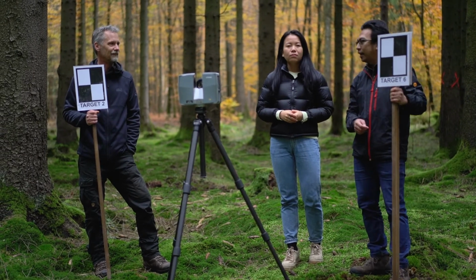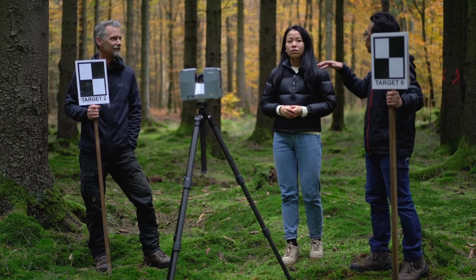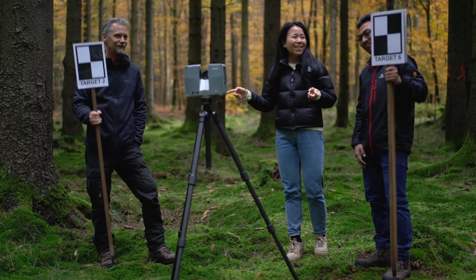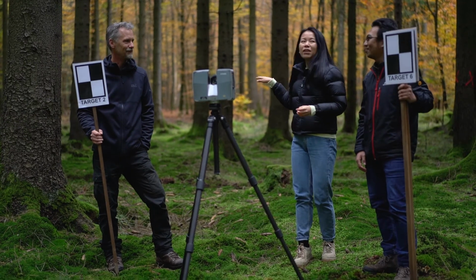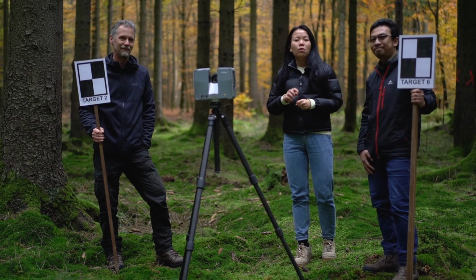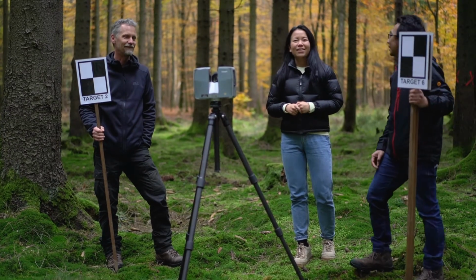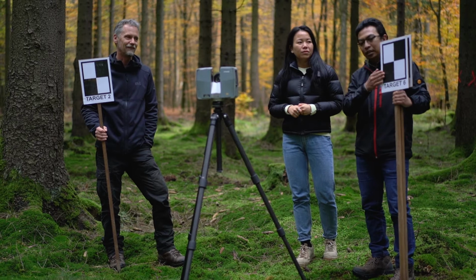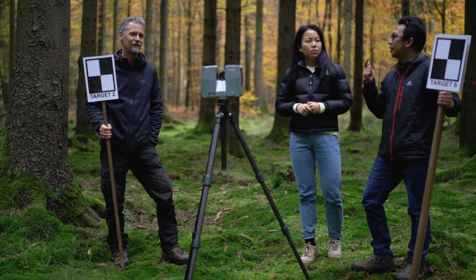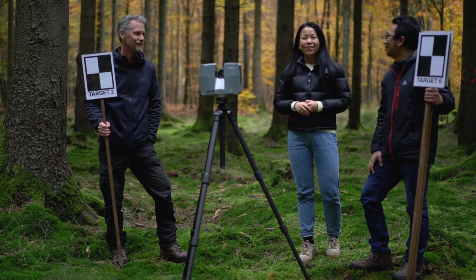Multiple scan positions, and we need them for registration. For this registration, we need the overlapping area or common points. Speaking about common points, that's why we need those targets. We can put those targets around the tree and use them for the registration. I think it's really important when we have a homogeneous landscape, like in the forest or in the grassland, right? Yeah, for sure. And we can even work without the targets as common points, for example indoors and for objects that have a special structure, we can do it like that also. Okay.